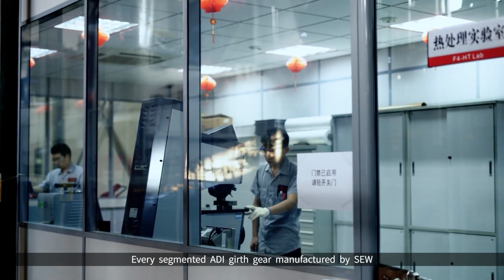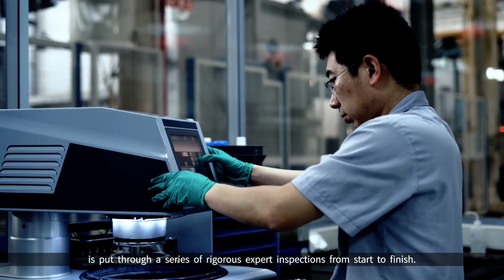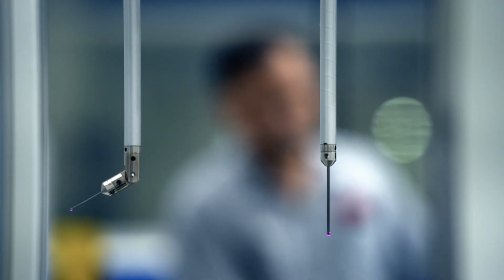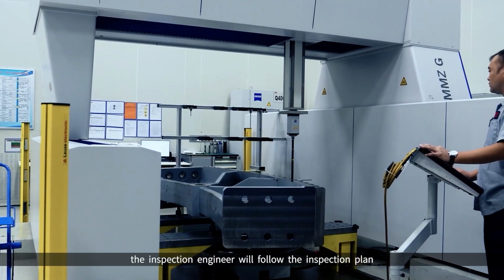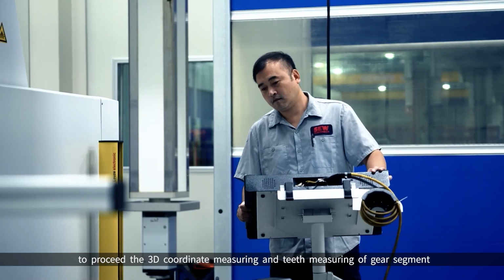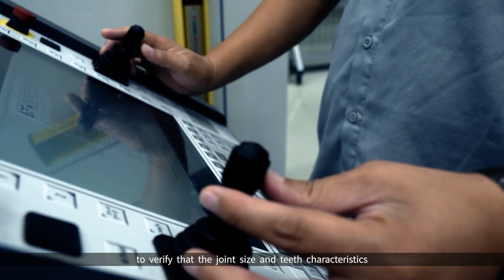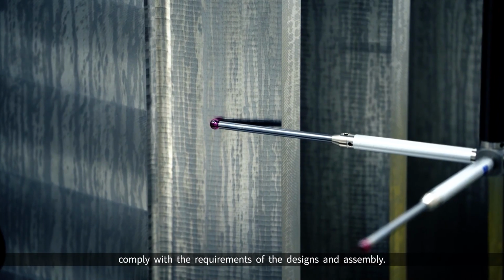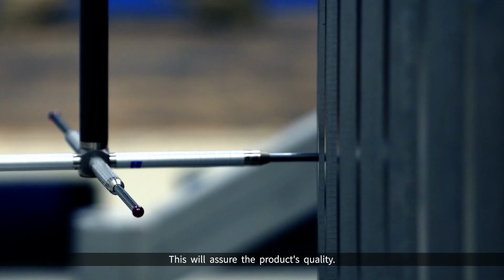Every segmented ADI girth gear manufactured by SEW is put through a series of rigorous expert inspections from start to finish. After the product has been finished, the inspection engineer will follow the inspection plan to proceed the 3D coordinate measuring and teeth measuring of gear segment to verify that the joint size and teeth characteristics comply with the requirements of the designs and assembly. This will assure the product's quality.